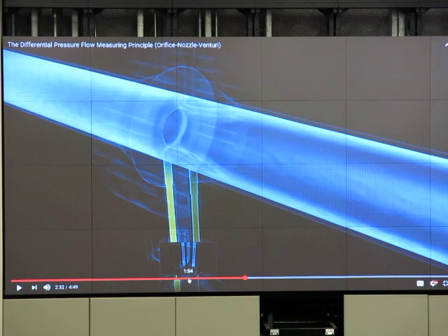There's a precise range on their website. For example, when we try to figure out what kind of orifice plate we want to use, they want to know the range of the flow rate. And when you download the manual, it says for this range, if you want to use this, we recommend model ABCD something. It even tells you the model number and the size. What they need to know is what kind of gas we want to measure. Okay, just that. Good.